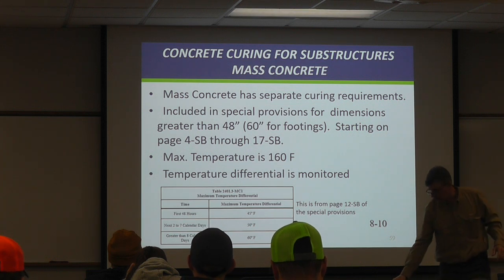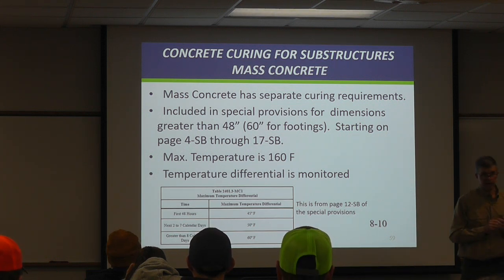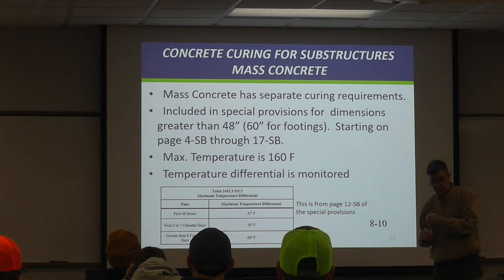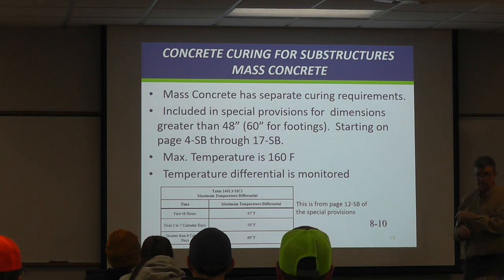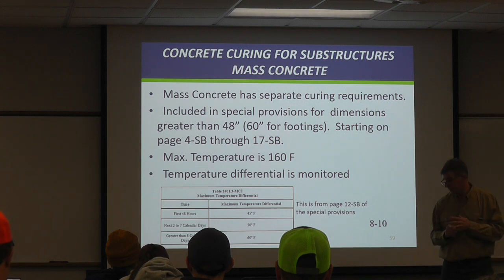Concrete, as it cures, generates heat of hydration. It can get very hot. The 35W video talked about how concrete literally can heat itself up internally from the reaction of all of the cement and the pozzolans and stuff. And so we want to control that temperature.